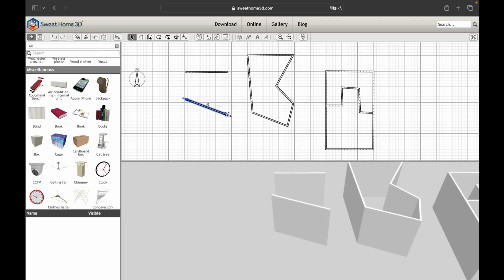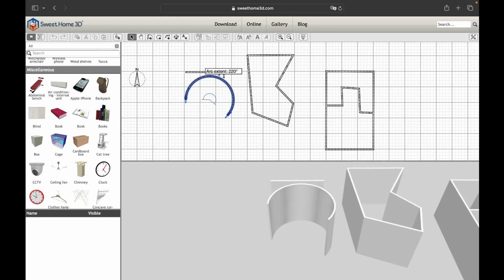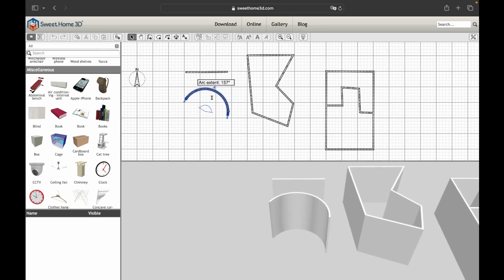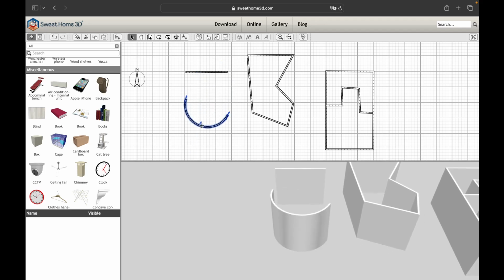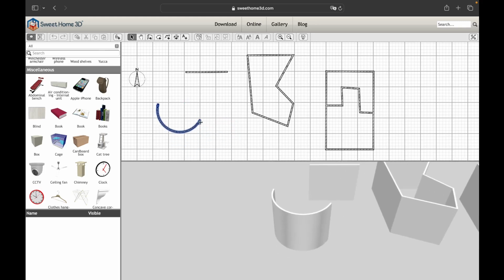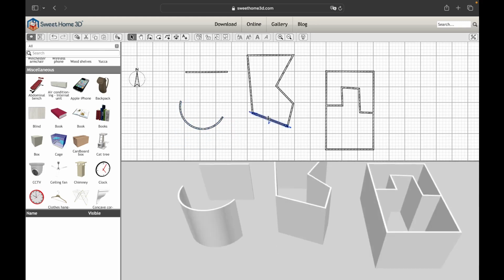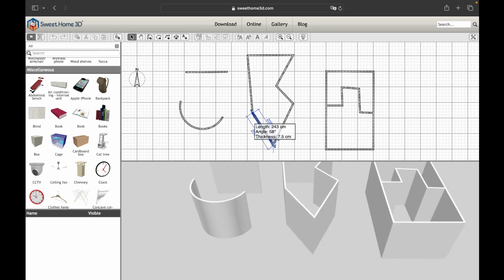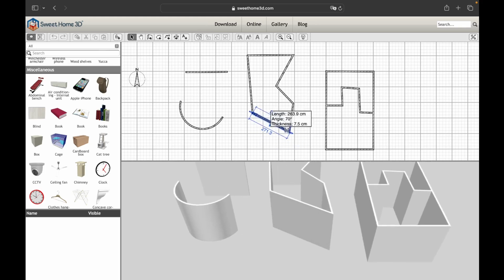When we select a wall, we can make it curved by interacting with the symbol located centrally by clicking with the left button and dragging the mouse to establish the radius of curvature. We can also move the wall selected in this way on the plan. If we have two connected walls and we only move one, the second will adapt accordingly.